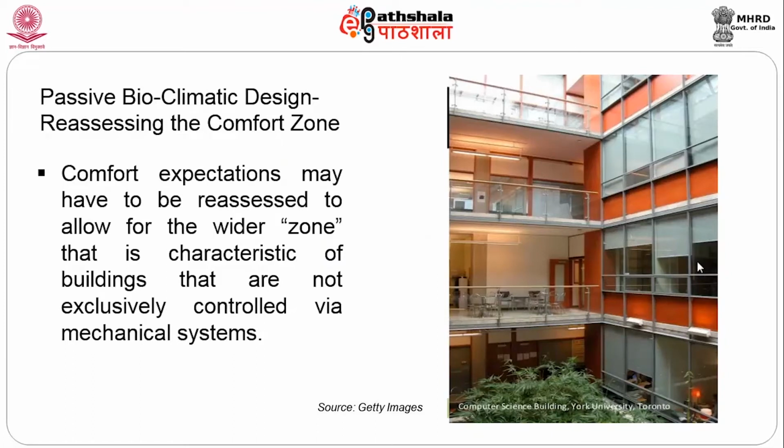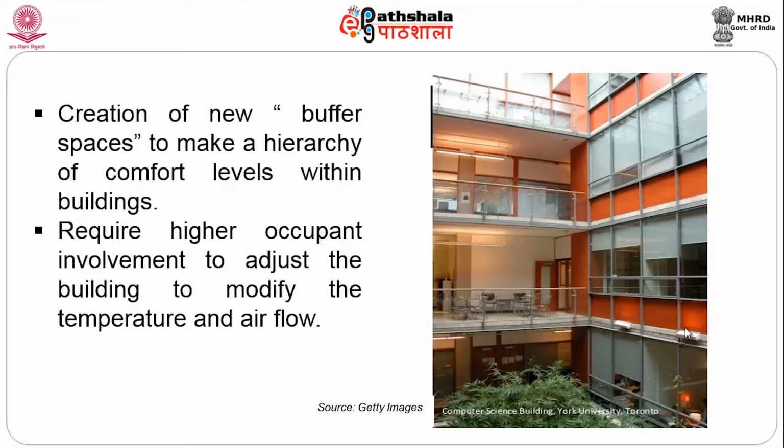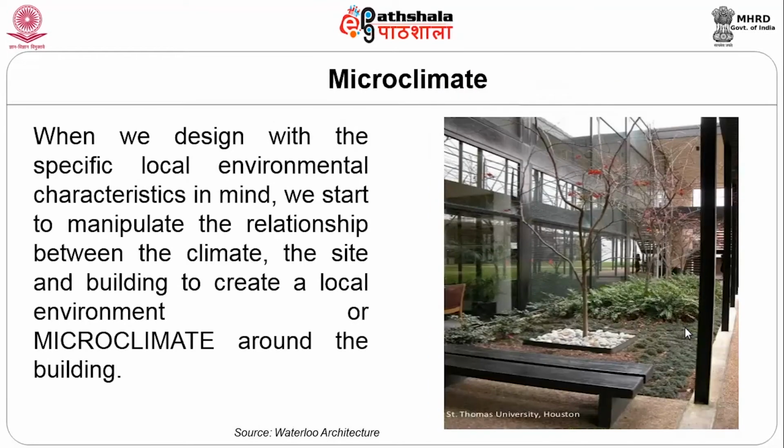Here we have an example of the passive bioclimatic design, how we reassess the comfort zone. This again is the computer science building in York University in Toronto. Comfort expectations may have to be reassessed to allow for a wider zone, that is characteristics of buildings that are not exclusively controlled via mechanical systems. It involves the creation of new buffer spaces to make a hierarchy of comfort levels within the buildings. It requires a higher occupant involvement to adjust the building to modify the temperature as well as airflow.